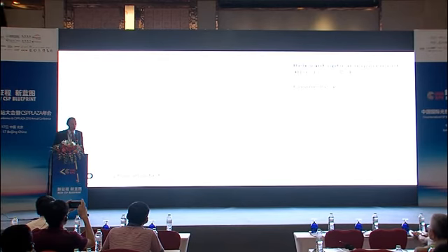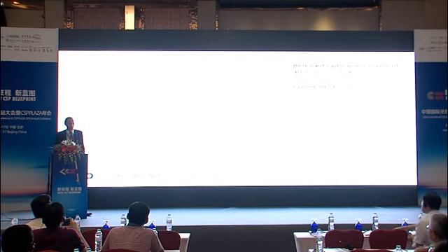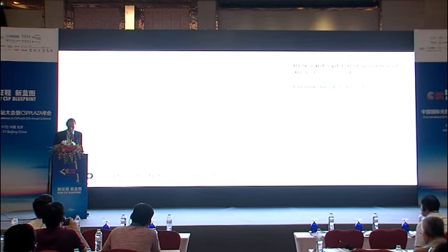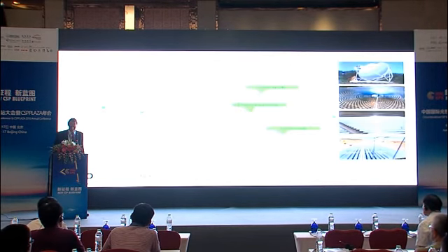Another loss is actually related to power towers quite a lot. You can hardly do anything against it. Maybe just build around the equator, that helps, but usually the choice is not that easy. But in this case, to prevent the cosine losses, you place most of the heliostats in the north, that's in the northern hemisphere, because then your plant becomes more efficient.